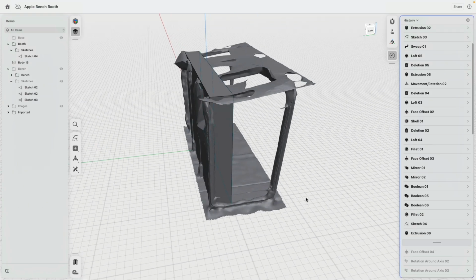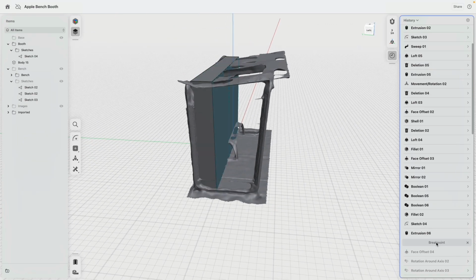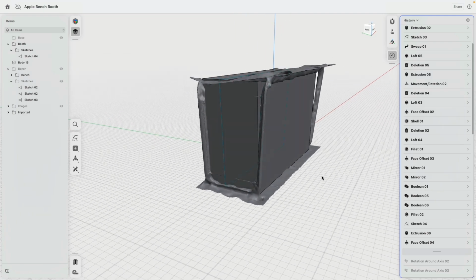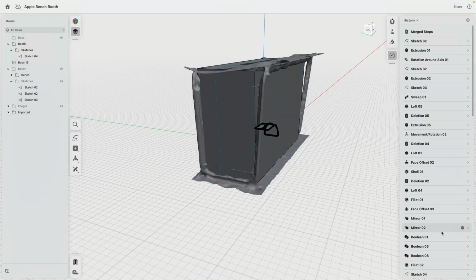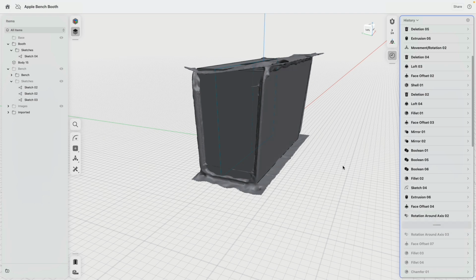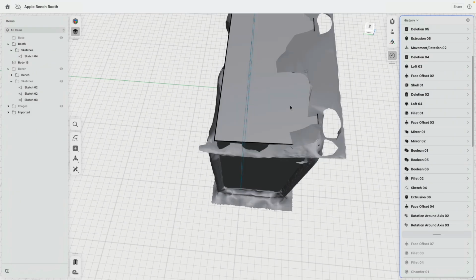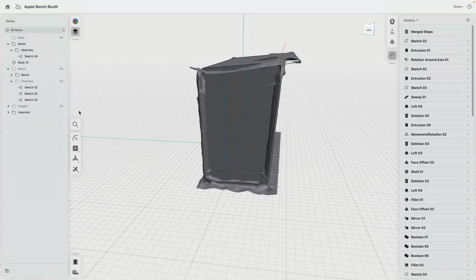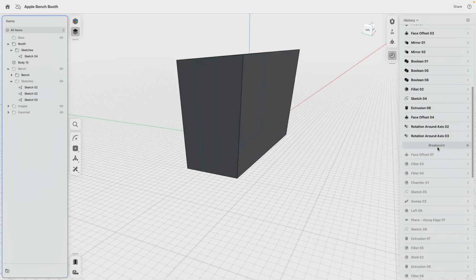And then I extruded that sketch backwards. And then I hit the sketch and offset the face to the front. Then I selected the front face and bottom edge, rotated that face, and then I rotated it also on top. So I select this face and this edge. It's a very simple command.